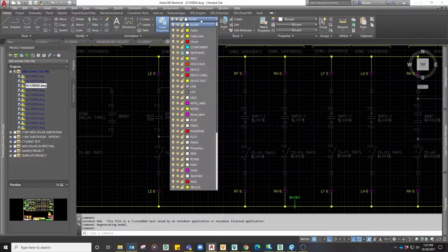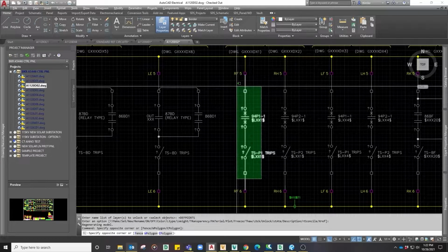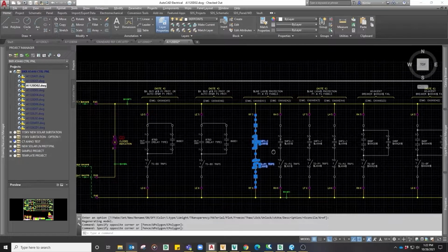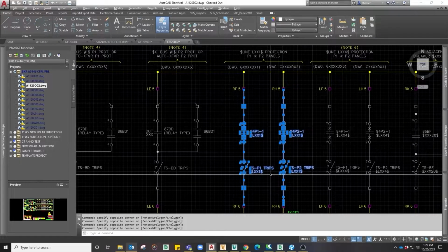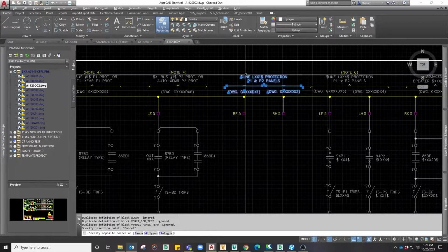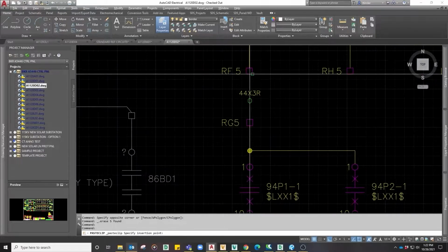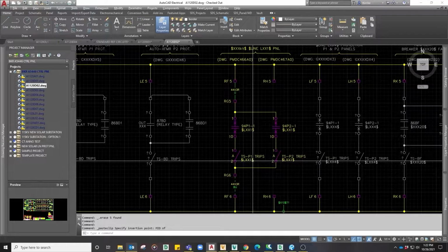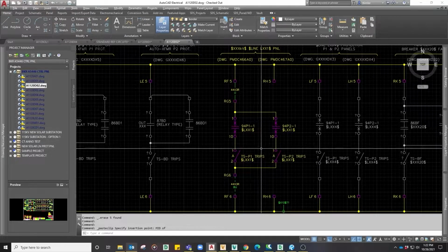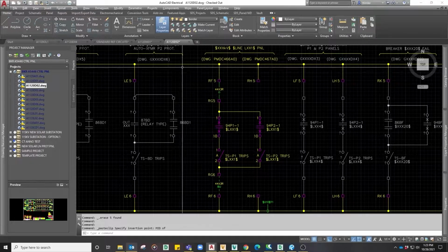Locate the terminal where it's going to be inserted onto, and then delete the template circuit that's connected to the terminals. Delete that grouping, the grouping right next to it, and I'll also delete the drawing cross-reference information and the circuit description information at the top. Now by doing a Control V, I'll type in MID for midpoint and snap that circuit at the midpoint of that schematic terminal. The midpoint of that schematic terminal is where the connection point attribute for that schematic terminal is located.